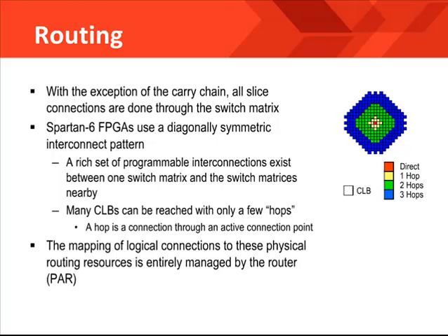The Spartan-6 has routing besides carry chain logic. It is routed through the switch matrices. While understanding the interconnect structure is seldom needed, this diagram is meant to describe the interconnection between slices and CLBs. You see, in between each CLB is a switch matrix which is designed to connect to other switch matrices as well as neighboring CLBs. The possible interconnects are called PIPs, or programmable interconnect points. Please note that proper use of global timing constraints, which is explained in the Essentials of FPGA Design course, is going to be required for you to obtain optimum speed.